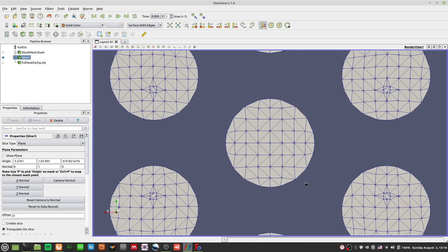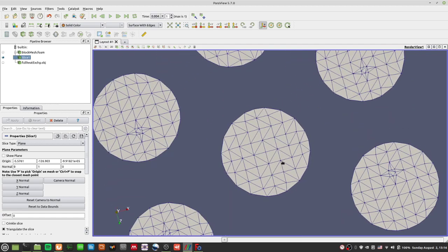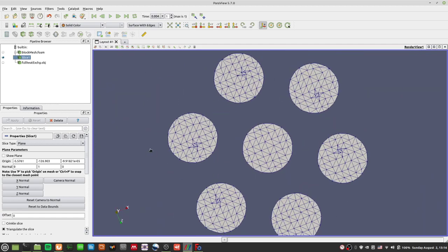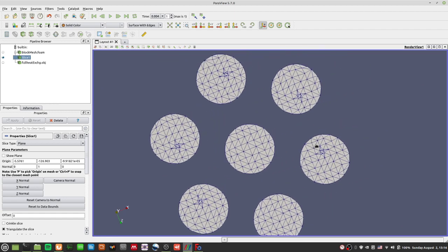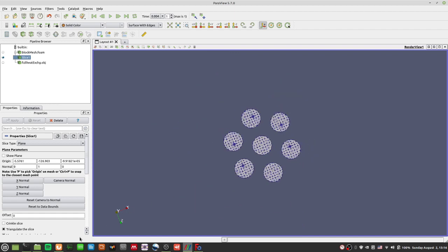Yeah, there you go. You won't see layers added because there was some problem with the layer addition process, so they did not add layers. If you play around with SnappyHexMesh and blockMesh, you will have that kind of effect going on. So what you'll have is what you see on the screen here. However, the checkMesh fails, so you're flying blind with this, which may not be the best idea.